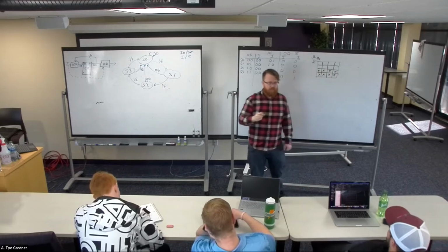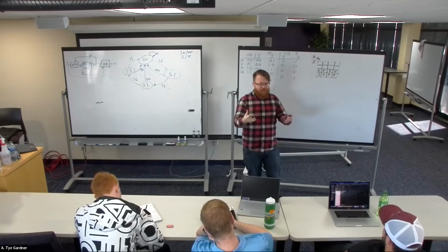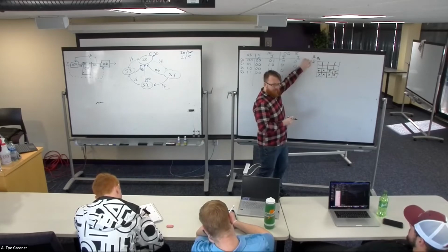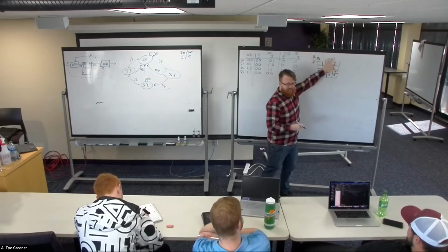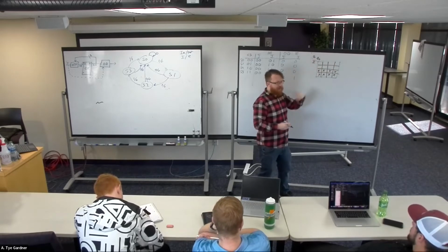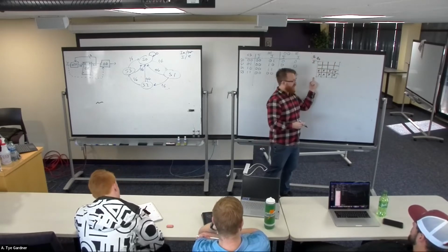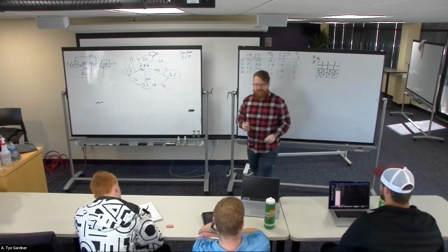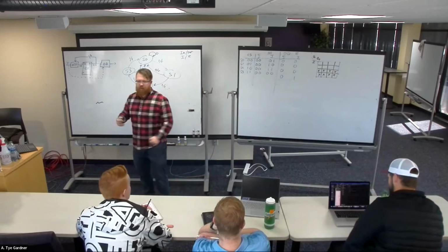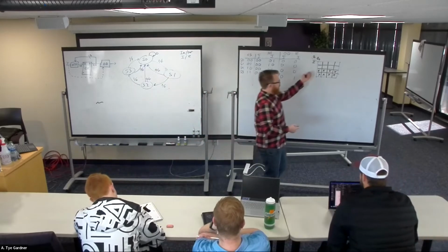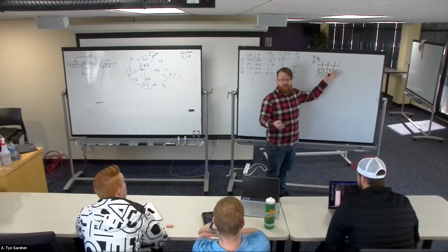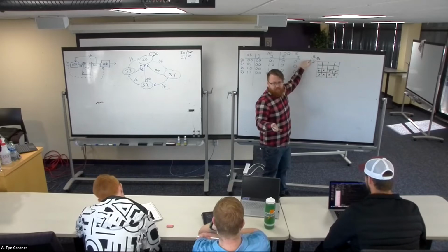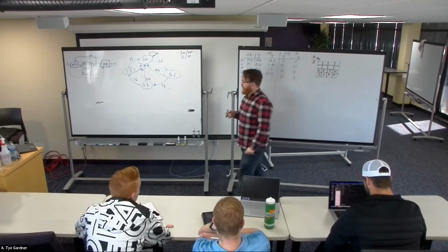Right? Can you just take off the bottom one that came out? Yes, I can. I just want to remind you that that's really what K-maps are doing. If I only have 1 here, that's why we can draw this 3 variable K-map. It really is a 4 variable K-map with just don't cares down here. It's I and X. Yes, exactly. So we can ignore that, or if we were to fill it out with the 1s and 0s, we'll end up with the same thing. Doesn't matter, because whatever variable is here will cancel out. No matter what we do, it'll cancel out as long as we get it right.